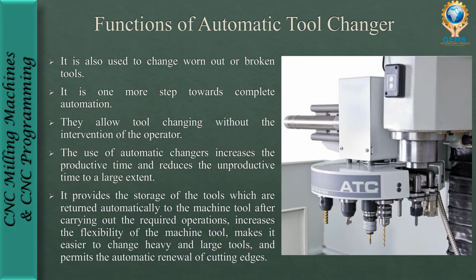It provides storage of the tools, which are returned automatically to the machine tool after carrying out the required operations. And it increases the flexibility of the machine tool, makes it easier to change heavy and large tools, and permits the automatic renewal of cutting edges. So it has a large storage with a number of tools. Once the tool finishes the operation, with an automatic tool changer it will come back to the storage, and it increases the flexibility of the machine tools.